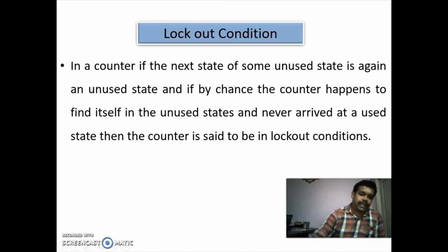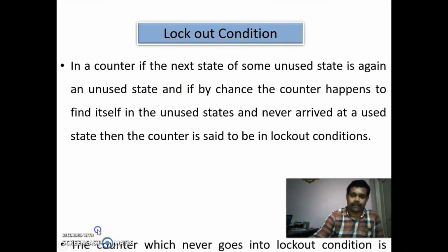In a counter, you are having some unused state, and the next state of that unused state is again an unused state, and if by chance the counter goes to that unused state, and it is staying there and it is not coming to the used state, then the counter is said to be in lockout condition.